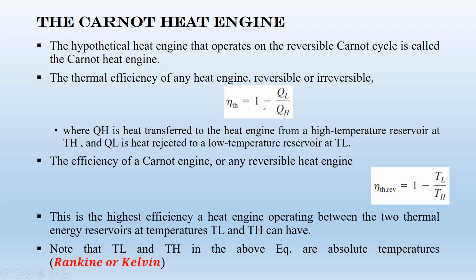So this equation is valid for both reversible and irreversible. This one is just for the reversible one. And then keep in your mind that the temperature must be absolute. Okay, what's the application of this Carnot heat engine? What you can do, guys, you can calculate the thermal efficiency. Actually, you can use this